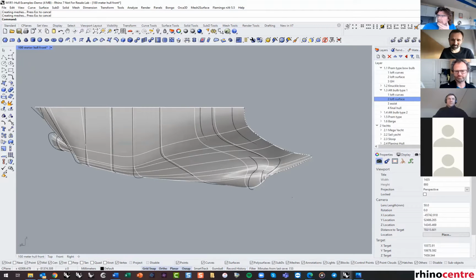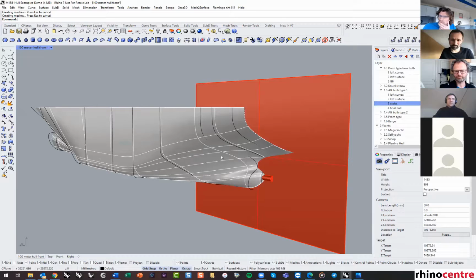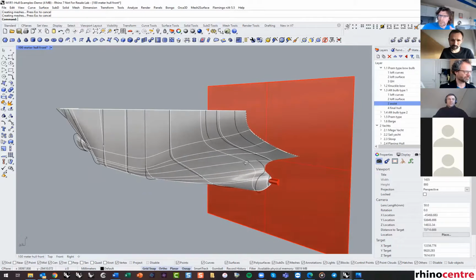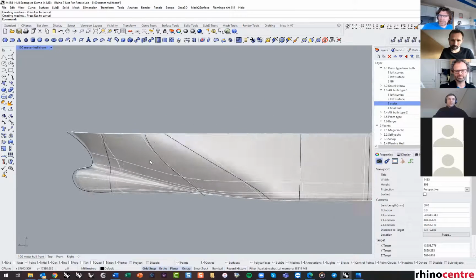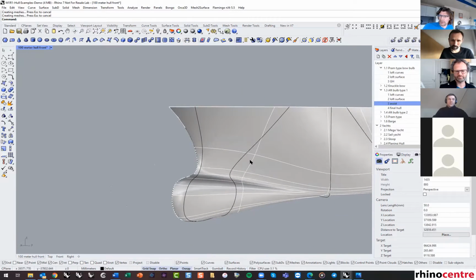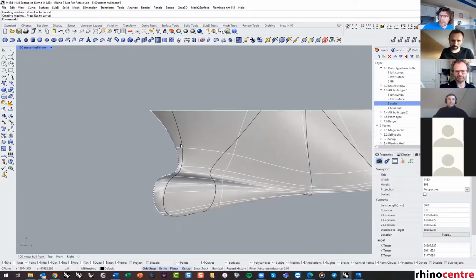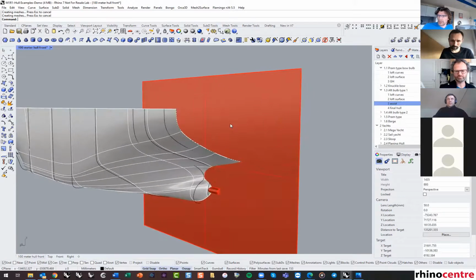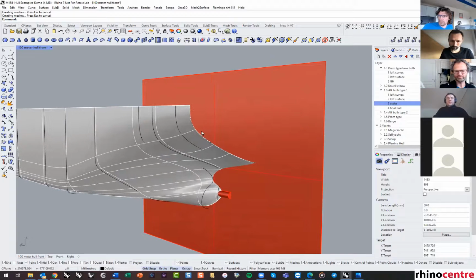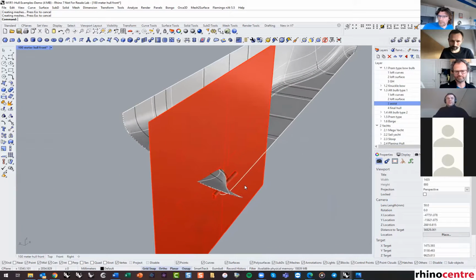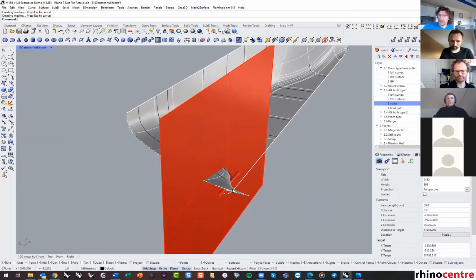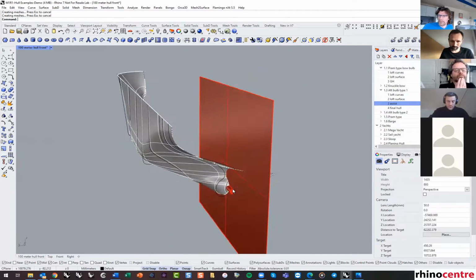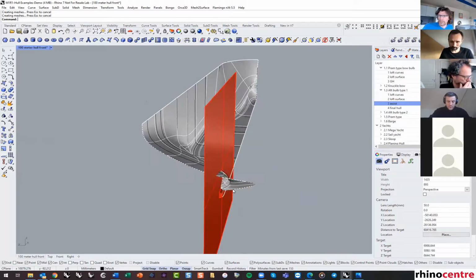And I also wondering, do you need to put some stem curve at the bow and the stern to make some boundary there? Yes, here you see that in the bow you have some stem curve. But not in the stern. Well, that's why your surface extended over the central plane. So you let it go intentionally at the stern part. Okay. Thanks.